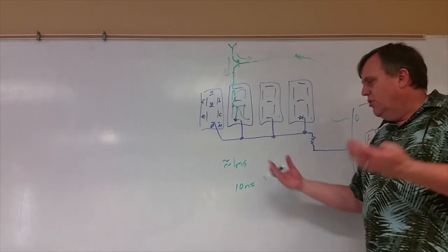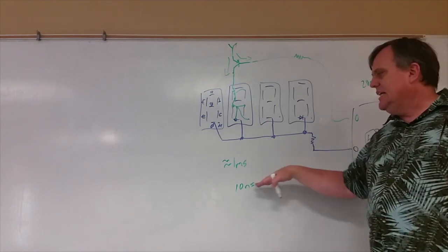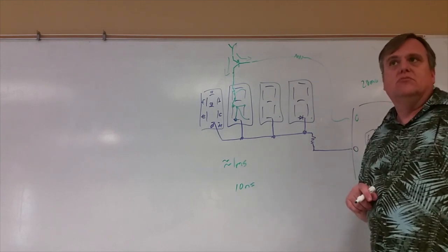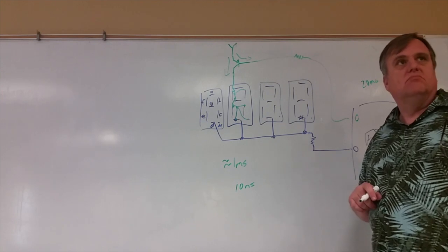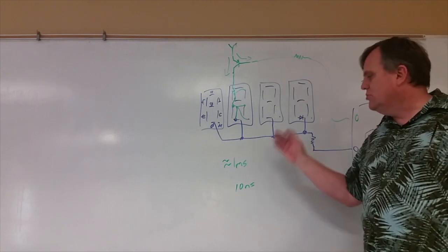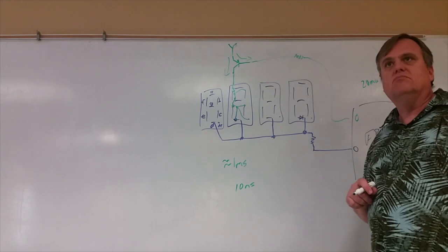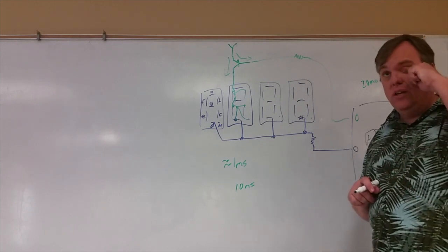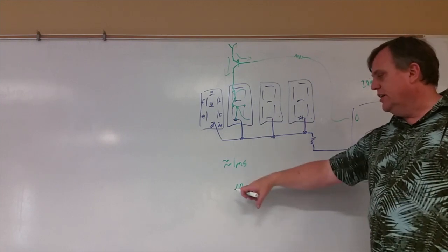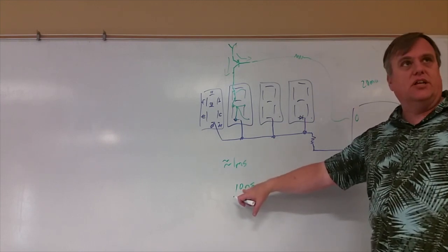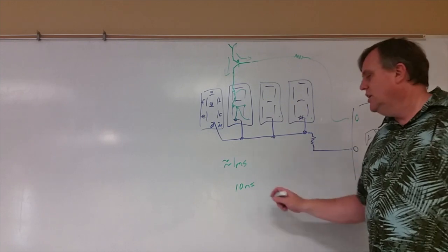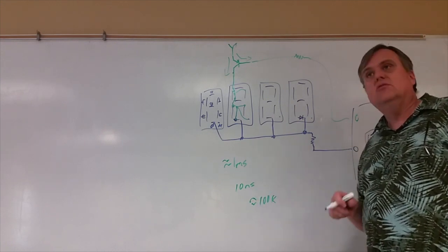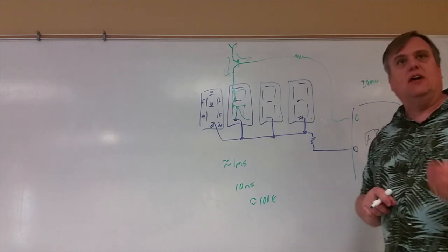So I get that ratio. So it basically takes 10,000 counts to get there. Actually, 100,000, sorry. So 100,000 counts will get me to a millisecond, because 100 gets me to a microsecond and then another 1,000 to a millisecond. So I need somewhere in the range of 100K as a counter. How big of a counter to get me 100K?